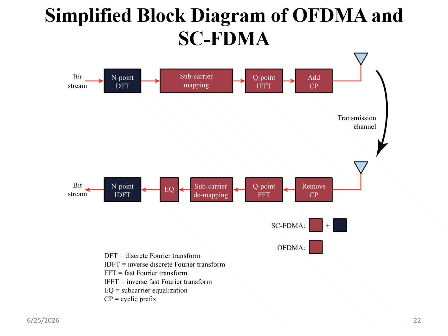Then subcarrier mapping. Here we map each carrier by subcarrier mapping. All carriers will be mapped, and then it goes through one more algorithm, the IFFT used in OFDM, that is inverse fast Fourier transformation. Then we add the cyclic prefix. Then with the help of a digital to analog converter, we transmit. On the receiver side, the IFFT becomes FFT. Subcarrier mapping becomes subcarrier demapping, with a parallel to serial converter and a serial to parallel converter.